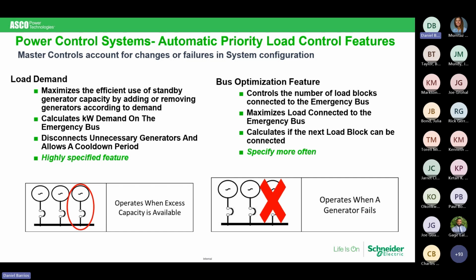As I stated before, just to make sure you get the emergency power up and running, all generators will start, they will close. After a period of time, and that time can be set, we say we don't need one of these generators, we don't need two of the generators, and we will retire those. They will be available for automatic starting again.